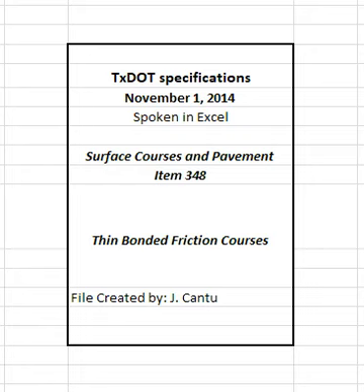2.7.1 RAP. RAP is salvaged, milled, pulverized, broken, or crushed asphalt pavement. Crush or break RAP so that 100% of the particles pass the 2 inch sieve. Fractionated RAP is defined as 2 or more RAP stockpiles, divided into coarse and fine fractions. Use of contractor-owned RAP including HMA plant waste is permitted unless otherwise shown on the plans. Department-owned RAP stockpiles are available for the contractor's use when the stockpile locations are shown on the plans.